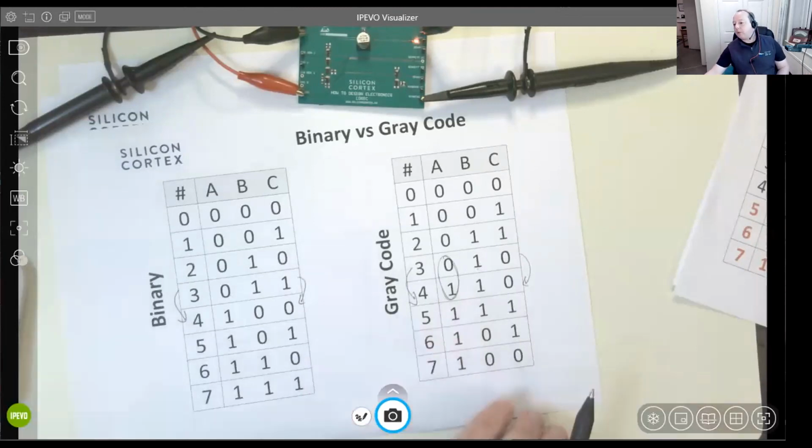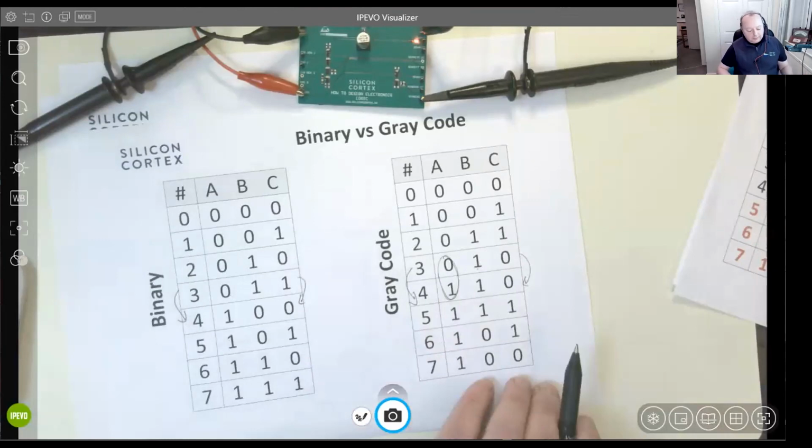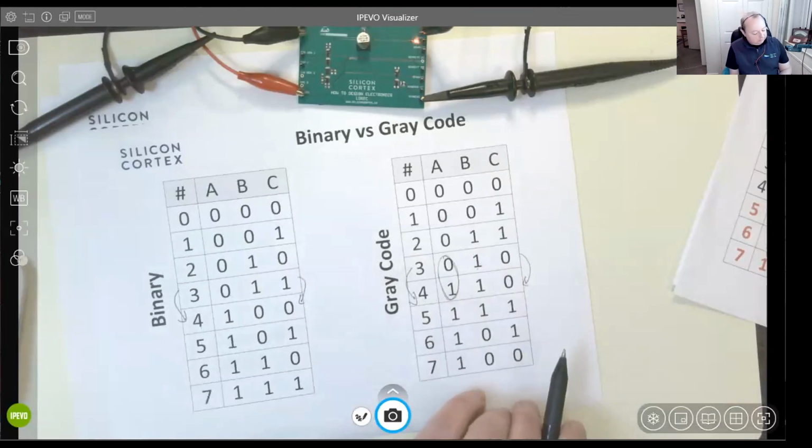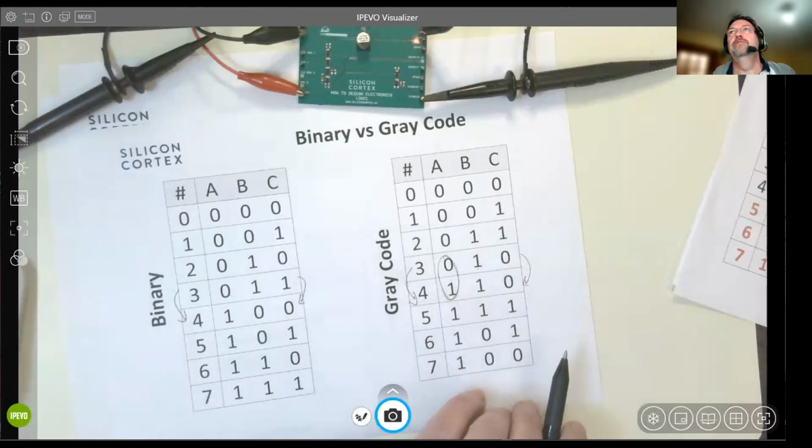The other thing is, when we're trying to go super fast, the faster you try and go, the more power you're going to draw, and the more radio emissions you're going to generate. So do you need to go that fast is the question. Yeah, the philosophy from where I've been sitting has always been design for exactly as fast as you need and no faster, because ye gods, EMC compliance is a pain.